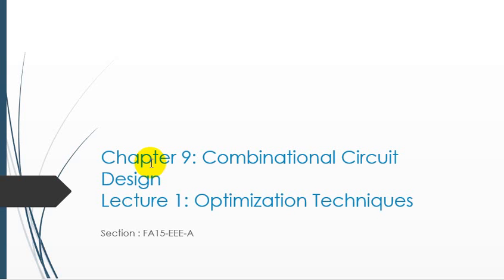So this chapter focuses on combinational logic, and the next chapter, chapter 10, examines sequential logic. In this chapter we introduce CMOS logic with the assumption that MOS transistors act as very simple switches. Static CMOS gates use complementary NMOS and PMOS networks to drive the 0 or the 1 output respectively.